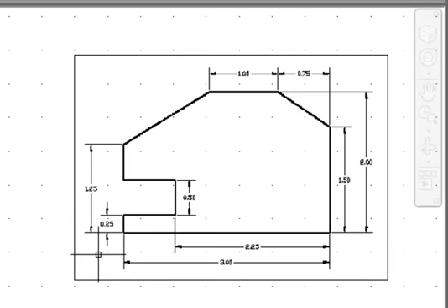Although we could set the snap and the grid display to smaller increments such as 0.1, the problem is that if you set the increment too small, it's more difficult to get the distance that we want. So in this case, 0.25 is a good choice. So let's set up the units and also set up the snap and grid display.